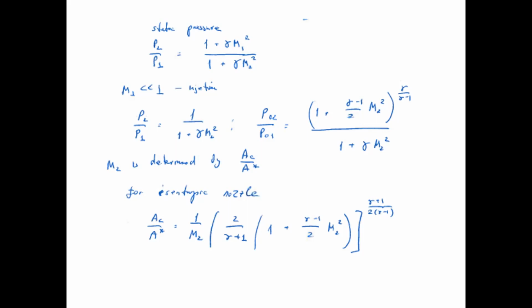So now, why do we need these equations? We need them in order to design the combustion chamber of the rocket and the nozzle. This equation can be used based upon the Mach number that you desire, and you can find out the ratio, or vice versa. You could decide on a ratio, and based on that, you can find out what the Mach number would look like for that kind of system. You could also do a plot to see how it varies with the Mach number.